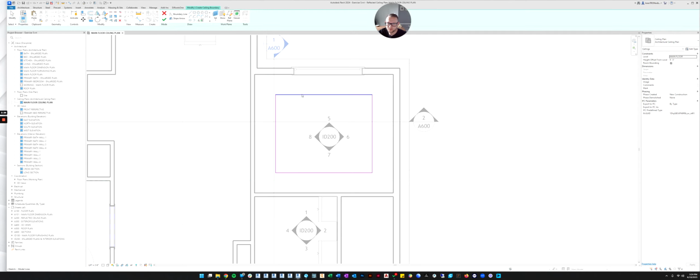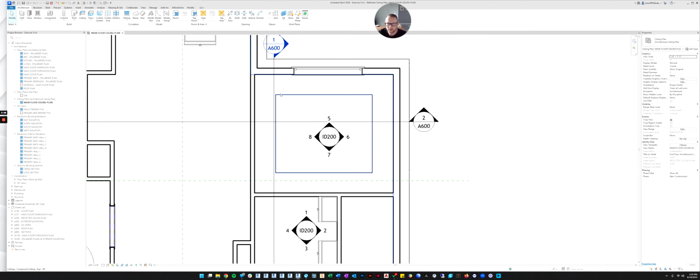Let's undo. It says it's going to make that generic ceiling. We want it to be our gypboard ceiling. And if the rest of the ceiling is 9 feet from the main floor, we want this one to be 10 feet. Okay, now we should finish. And I'm still not sure why it's not letting me select it.